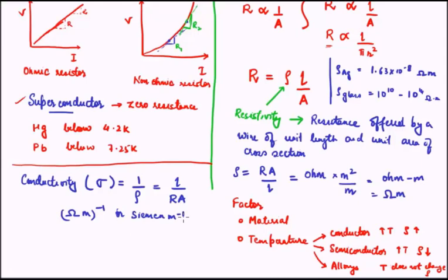Now we have seen the different concepts connecting resistance, resistivity, conductivity, material properties that affect it, and temperature. Depending on the application where we are going to apply the material, we choose the material. If we are going to do house wiring, we don't really want a material that will have high resistance that causes a lot of energy losses. We want a material with very low resistivity or high conductivity, like aluminium or silver or copper.